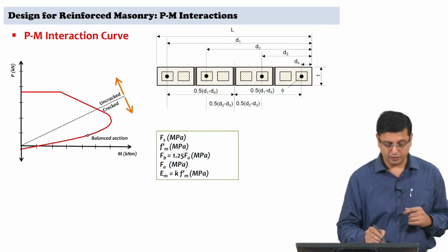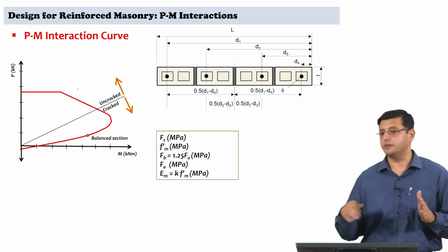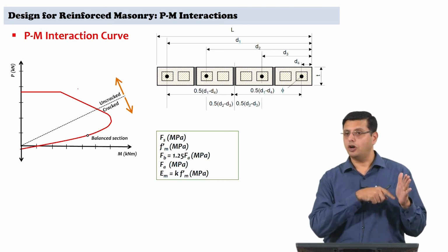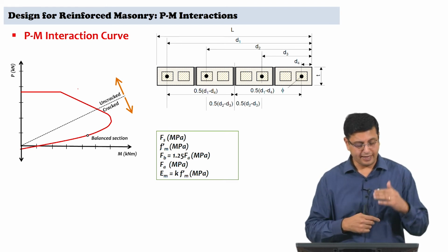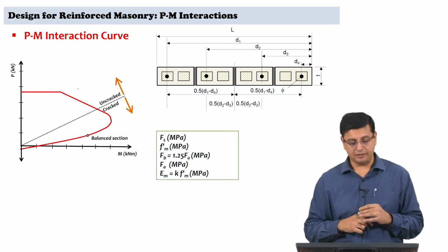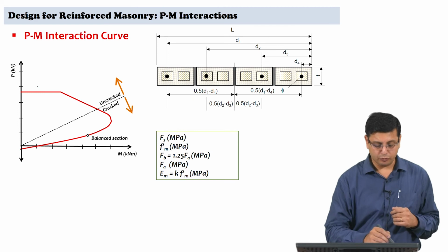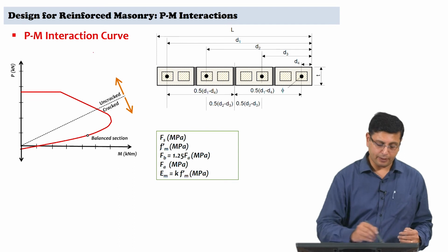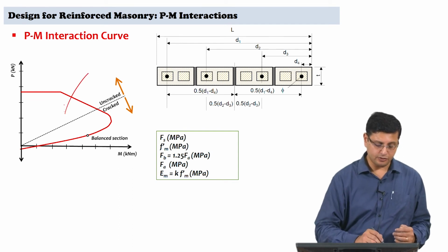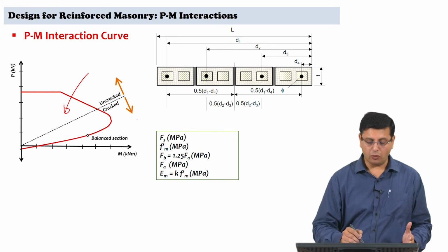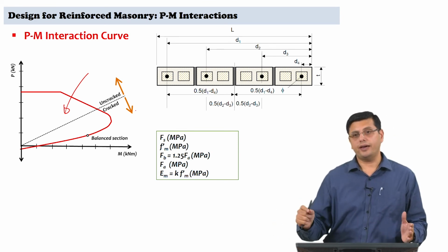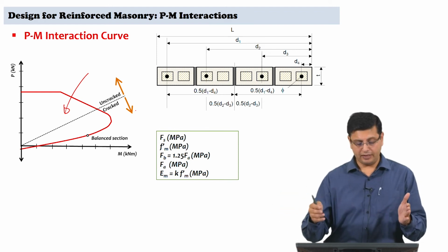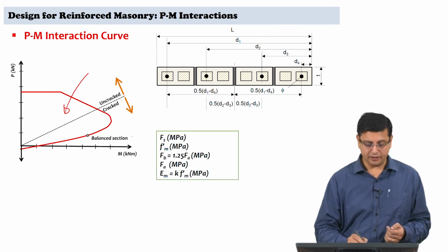The reason why it is capped off is because we are starting off with a peak capacity in compression on one end. So you are capping it off as far as the permissible compressive stress is concerned. So that would be your zone 1 all the way till it cracks. The upper part of the graph is zone 1, and then the wall cracks. After the wall cracks, you get into your zone 2 calculations where you are basically reducing the compressed length alpha L, and then you reach the balance section in this state.